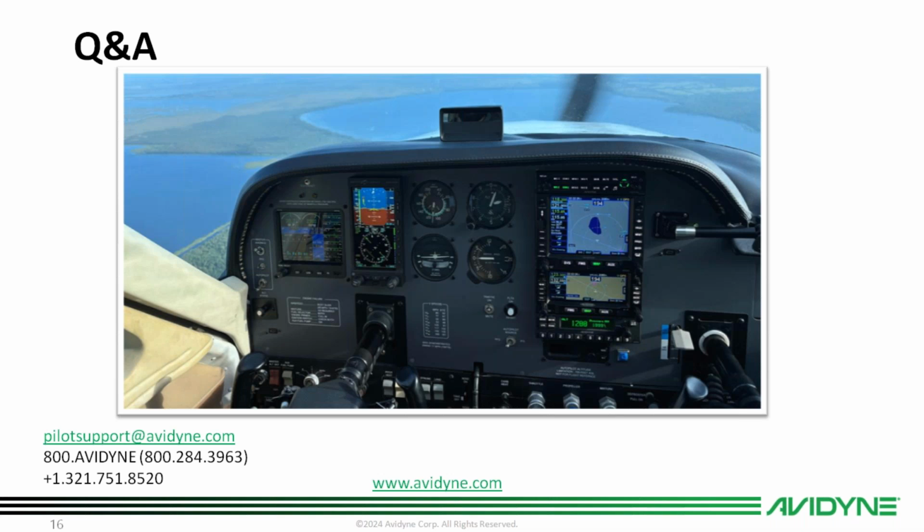The IFD is looking for UDP 4000 or Capstone protocol, and that's configurable with the Stratus Horizon app. So if you have a Stratus 3, it'll work. There are several ADS-B in devices out there that can do that, the Stratus, the StratTux as well, and the Level products.